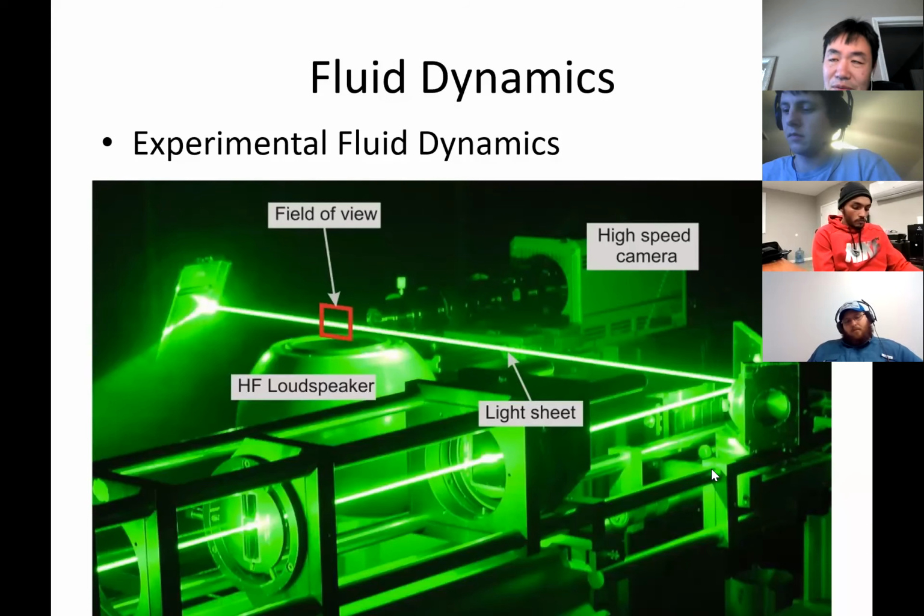In fluid mechanics, fluid dynamics, the difficult part is the flow, because it's invisible. Without knowing the flow, without knowing the velocity and accelerations, there's no way you can find out the force. So the major part of experimental fluid mechanics is to determine the velocity field.